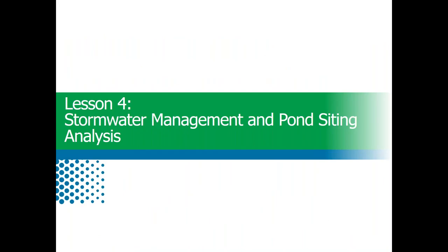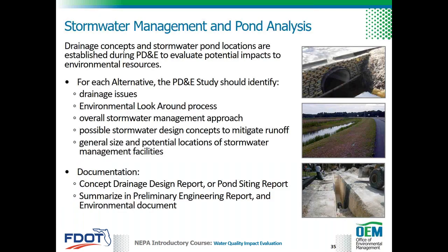Lesson 4 is stormwater management and pond siting analysis. Stormwater management, including pond siting, is established during PD&E. For each PD&E alternative, analysis is required to identify drainage issues, the overall stormwater management approach, design concepts to mitigate runoff, and estimate general size and potential location of stormwater management facilities. The documentation is either a concept drainage design report or a pond siting report, and is summarized in the environmental and engineering documents.